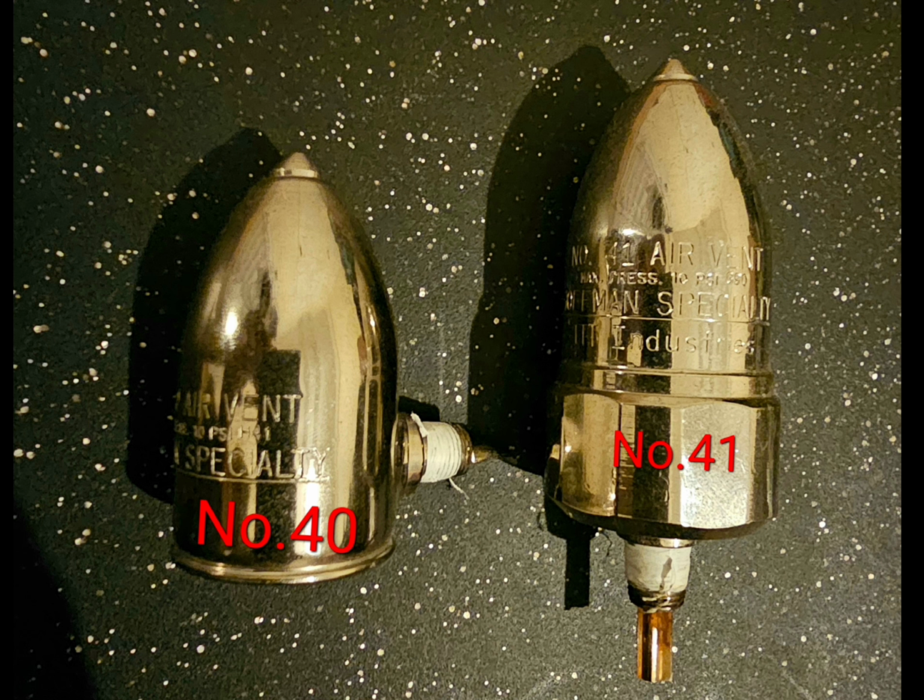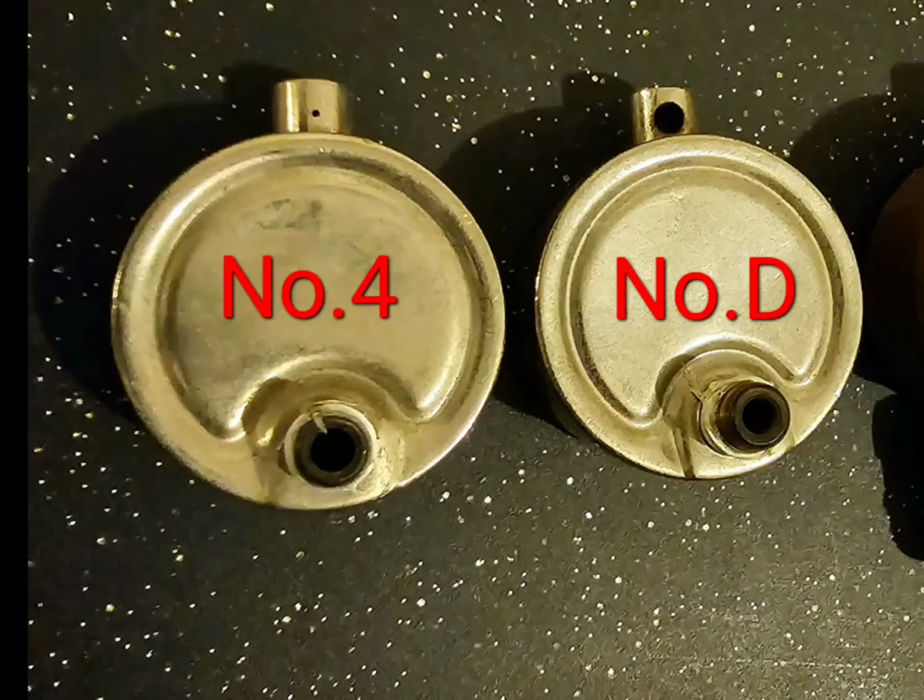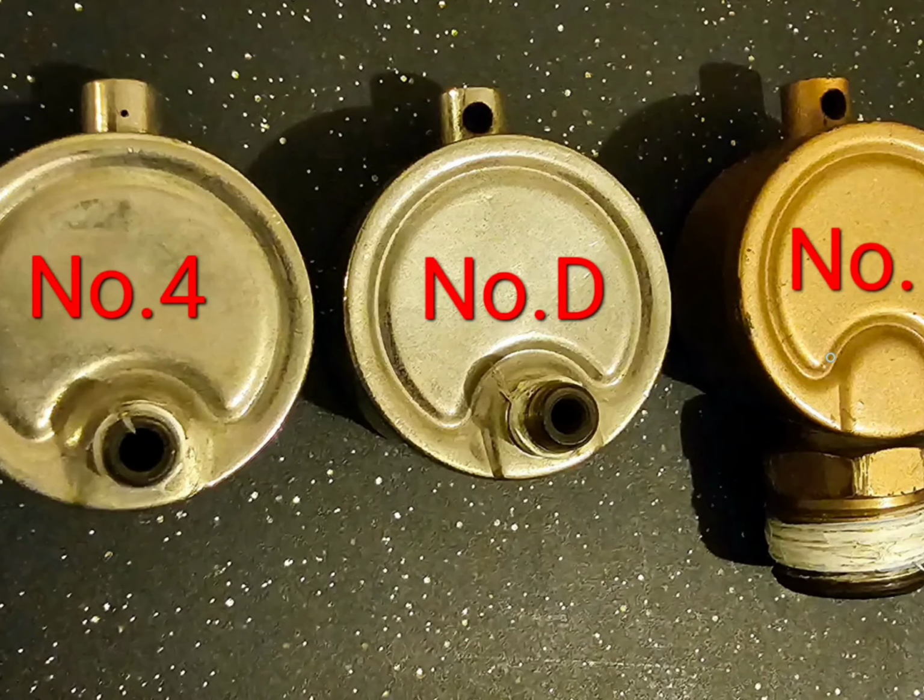The steel convector, if you have a vent that doesn't work properly, I'm not going to even say work properly, but if you put on a crappy vent on the radiator, what you're going to notice is the radiator is going to heat up excessively fast. So you decide to go ahead, and I'm going to get to this heat timer vent in just a minute. But if you decide to go, let's say, a Gordon's air vent, right? A number 1. Because you figure, oh, it has a large opening and this radiator is going to heat up excessively fast. You don't need to worry about doing that for a steel convector because they don't hold large capacity, which is also another reason why they cool down so fast. They have a lower steam capacity and a lower water capacity than self-standing cast iron radiators. So you don't have to worry about putting the largest vent on there to get it to heat up.